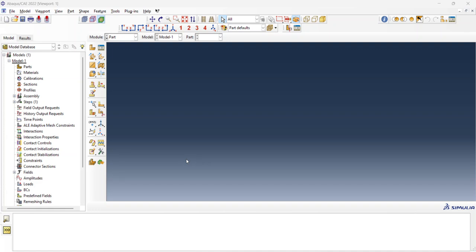Hi everyone, I'm going to show you how to get the magnitude of the response when doing the modal analysis in Abaqus. Basically in FRF, when you take the result, it will show you just the real part of the response, so you will see anti-resonance. In order to have just the peak in the response, you have to force Abaqus to show you the magnitude of the response, which comes from both the imaginary and real part of the response, not just the real one.